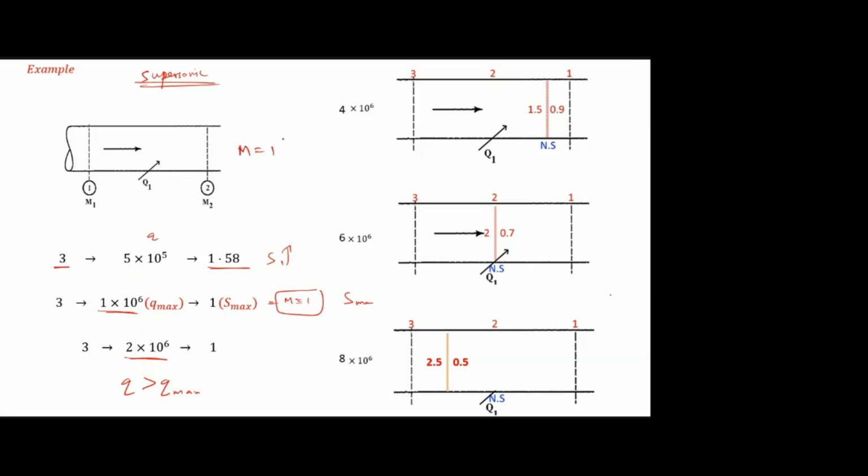Again, this side it is fixed. We cannot decelerate further. So this side we have Mach number 3. It keeps on decelerating. Finally, choking occurred. So now I am adding a Q value which is greater than Q max. This side it is fixed, we cannot change it. And this side also it is a very high momentum flow, because it is supersonic flow, right?